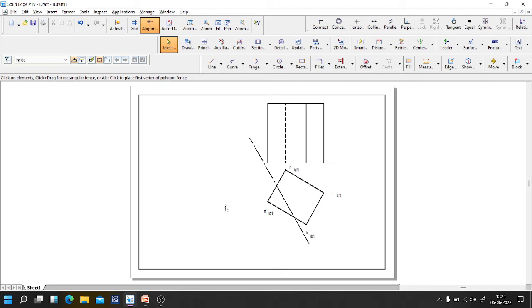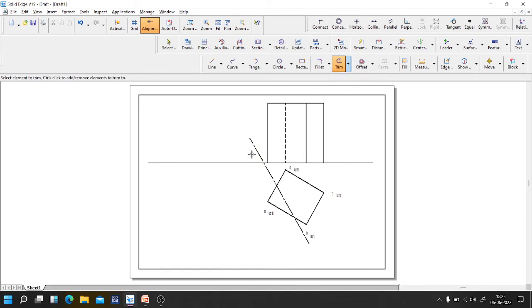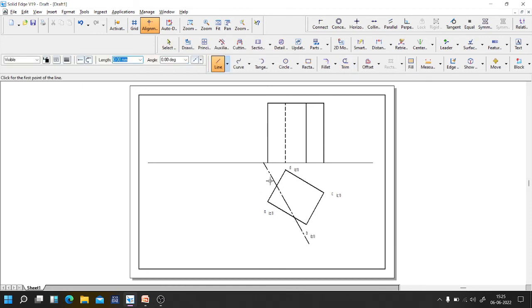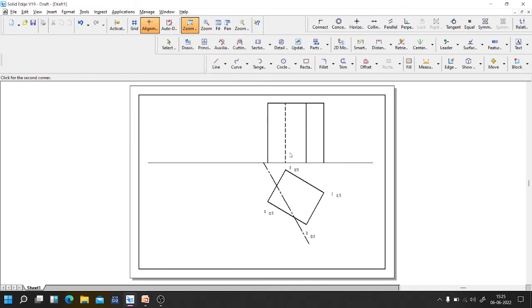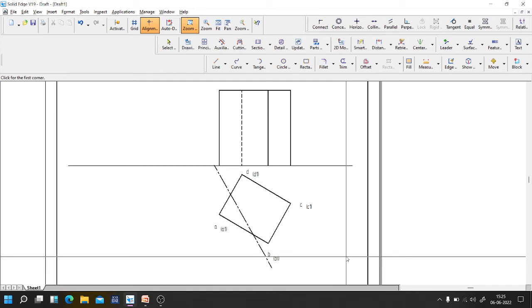Okay, now you just convert this one in the form of section plane, right? Section plane. Now if you are getting more portion, you can just remove this one. Now draw one line parallel to the section plane to get an auxiliary inclined plane. Now, before going to start the true shape of section, I will name the intersection points.